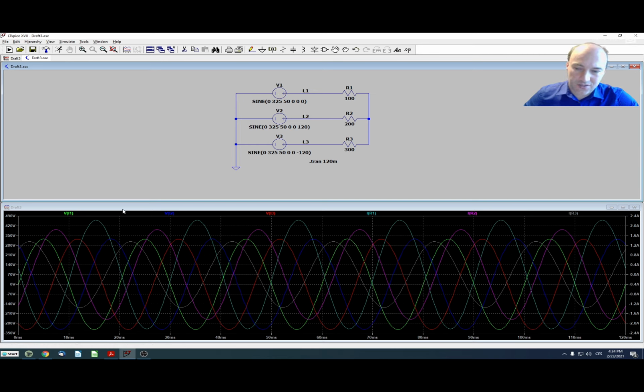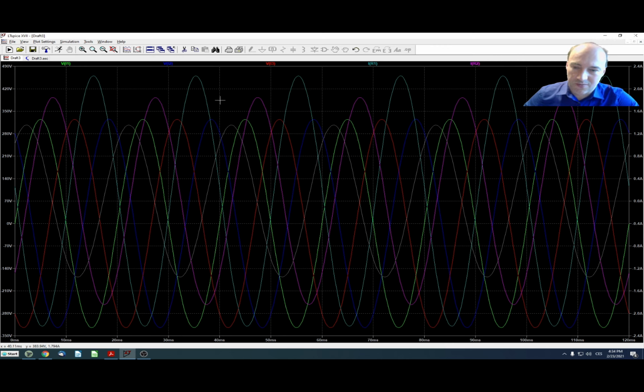So in the chart we will see that it looks like the phase shift between my current and my voltage is 180 degrees. But we have a resistive load, the phase shift is 0. This is only due to the reason that here I measure the voltage, for which this probe is positive, but the current probe is going in the opposite direction.